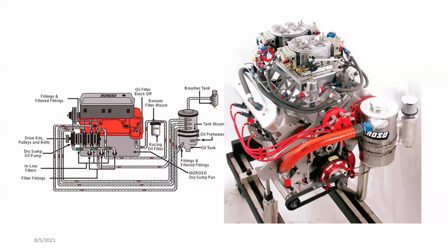It's going to create a sort of pressure because of the vaporized lubricant. That pressure has to be vented out, but venting it outside is not advisable because of emissions. So the vent is sent through something called a breather tank.